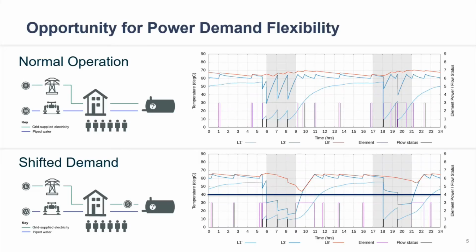In terms of normal operation, let's say, once again, we have a house, we have 6 occupants, and we have nothing else that we're worrying about. So we just have a geyser, no external switch. This is what we could expect as one of the load profiles we would see. These 3 trends are your temperatures. We have the top temperature at the outlet, the middle is the thermostat, and the bottom is the bottom of the tank, so it's the coldest part of the tank.